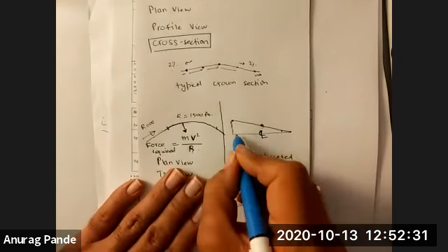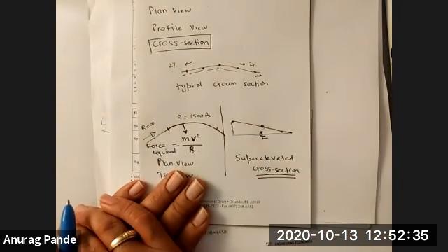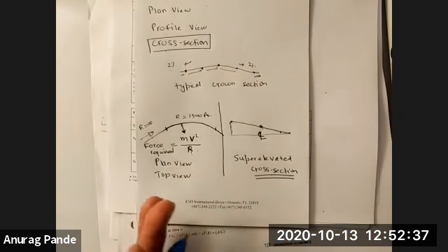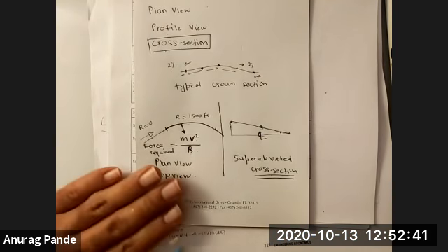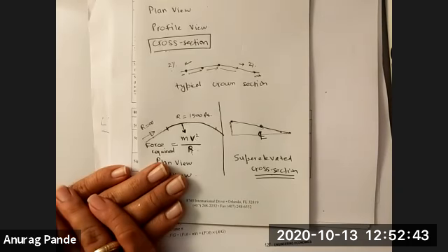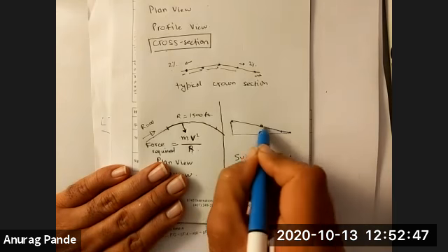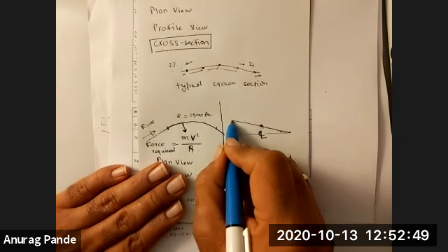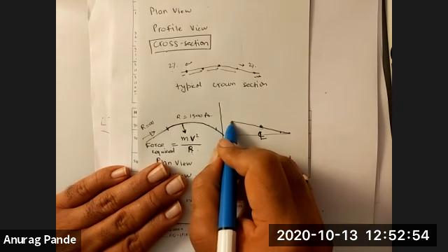And we design that 8% super elevation. But on urban roads, we typically limit ourselves to 4 to 6% because urban roads might have congestion and they don't have as high a speed, so they don't require as much super elevation. Okay? Now, the more super elevation you can provide, the smaller radius you can provide for the same design speed.